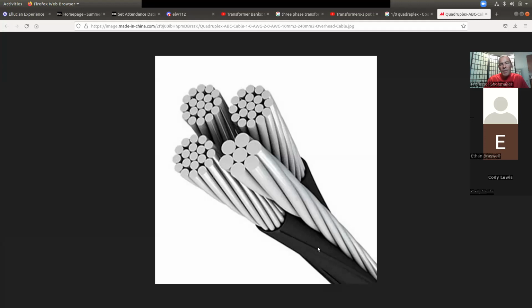When you go to the other end and you get ready to hook it up in the meter base, now you know what it is on the other end. It just has ridges in it. Some of your conductor companies will also put an A, a B, and a C stamped in, with white lettering, A, B, C, and the footage on the conductor. And you'd be able to say, well, A hot, B hot, C power. So that's how you discriminate from end to end.